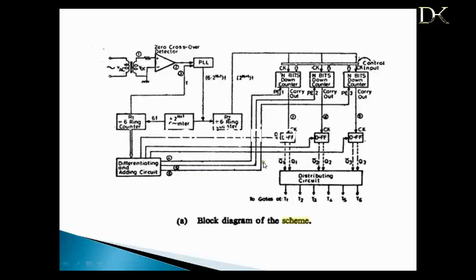The carry output of the down counter, carry out, gives out pulses after the counting is completed. This information along with the synchronizing waveform is fed to generate a phase delayed 180 degree wide pulse at the output of a D flip-flop.